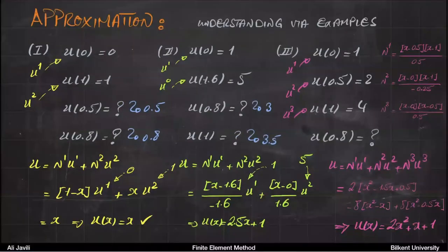And you can see, in order to get this, we did not solve 3 equations, 3 unknowns. We just used exactly what we had in our problem. We used the coordinates, we used the shape functions. So you define these shape functions once in your code, or in your lifetime, basically, in your programming. It's at the beginning of your code, and you can always reuse them for the next derivations.